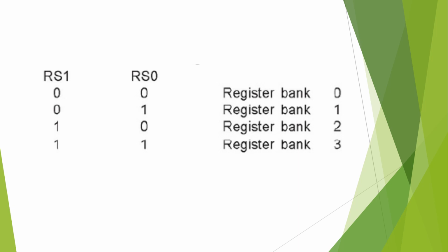One is the accumulator, which is used for addition and any kind of arithmetic or logical operation, and the register B, which has a special function. It can be used as a simple register, or it must be used in multiplication and division operations. That is why these two registers in the 8051 are known as the math registers.